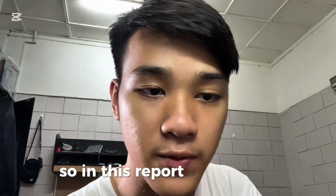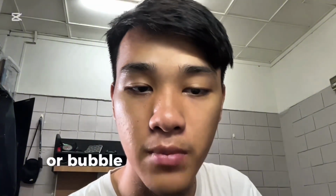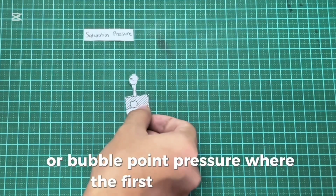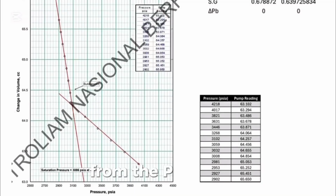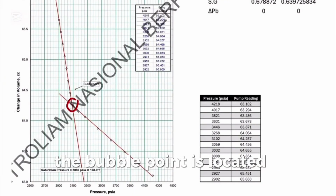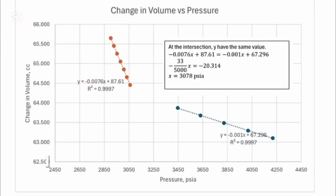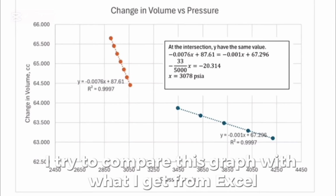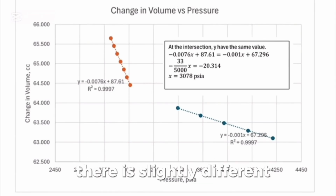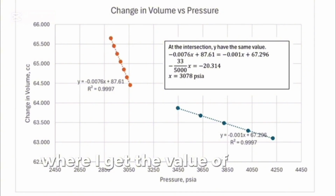So in this report fluid sample, we will determine its saturation pressure or bubble point pressure, where the first bubble is formed after expanding the fluid's volume. From the PVT report, the bubble point is located at a pressure of 3086 psia. I try to compare this graph with what I get from Excel. There is a slight difference in bubble point determination, where I get the value of 3078 psia.